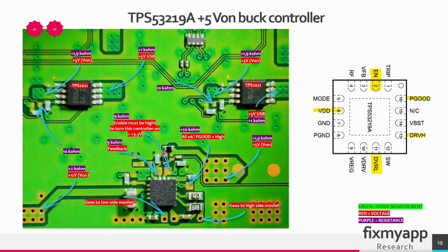So the resistor dividers provide feedback to the controller by dividing the output voltage to a manageable level. So it will bring this level down and it will go into this controller. If you can identify the resistor dividers, then you can see that it's connected to the output voltage and to the buck controller on the feedback pin.